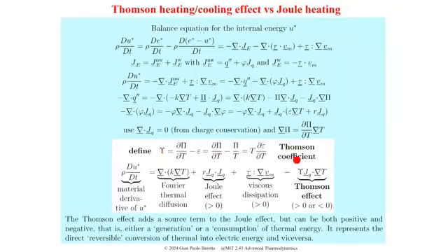The Thomson coefficient is, if you follow the various steps, at a certain stage, since there is the divergence of the energy flux, it brings in the gradient of the Peltier coefficient. And the gradient of the Peltier coefficient can be written as how it varies with temperature, partial of pi over partial T, times the gradient in temperature.